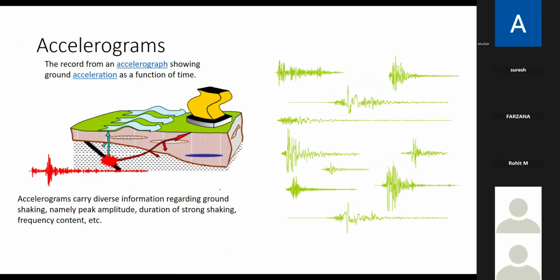So then next comes accelerogram. An accelerogram is an instrument which shows our accelerogram plot. It plots x-axis time, y-axis acceleration or displacement. If you integrate acceleration, we get velocity, integrate again, we get displacement. These are different earthquakes, in acceleration format. You can see here high, less. This earthquake has a very high time duration. Here initially very small, then suddenly high.